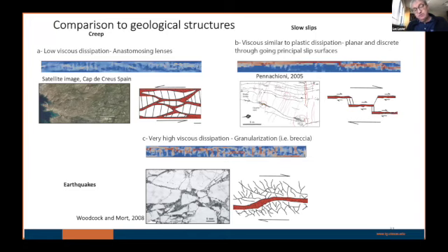This is very different from the previous model. Right now, I haven't been able to take the Mohr-Coulomb behavior and really match both the state and rate behavior of the rate and state, the empirical view of it. So if I would take one of these models and try to do the same thing as before, I wouldn't be able to get this kind of aperiodic and chaotic behavior like in the fault zone that I modeled in the previous part of the talk.